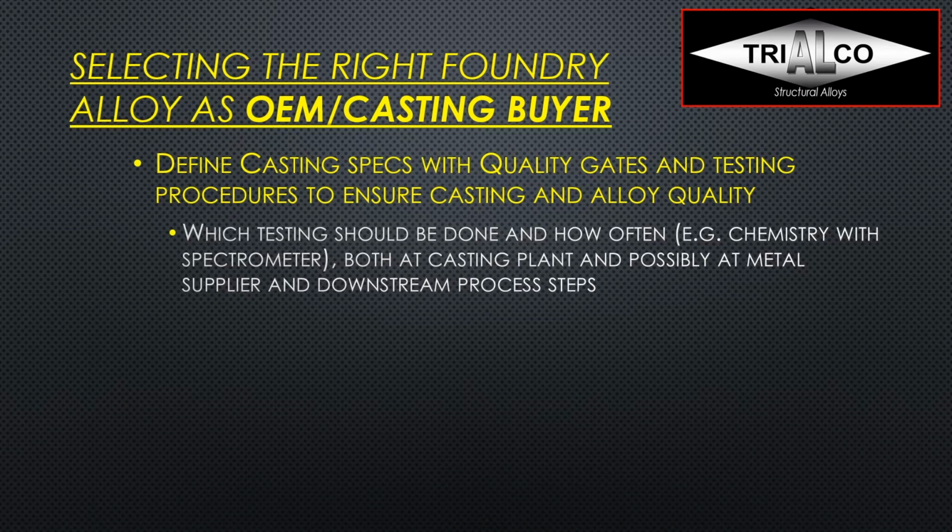For example, chemistry with a spectrometer, you want it to be done every time you melt it. And if the furnace was sitting overnight or over the weekend and you start back up Monday morning, you want to have it tested again. You might want to have this tested both at the casting plant and possibly at the metal supplier and even downstream process steps. So all the testing that you want to have done, and when, how often, specify that.